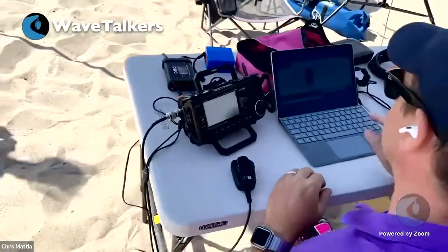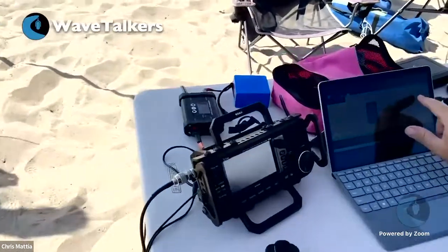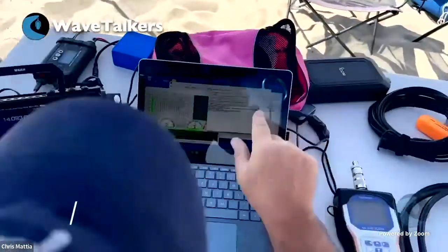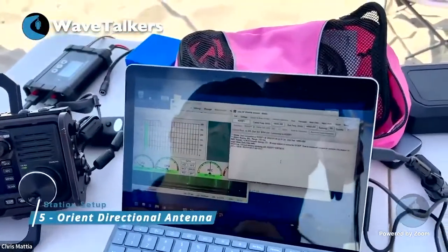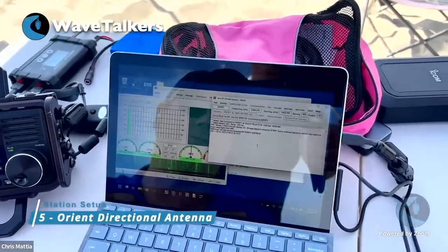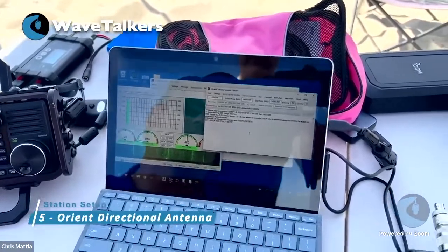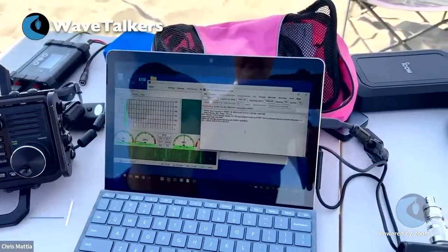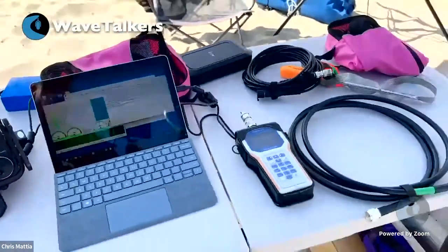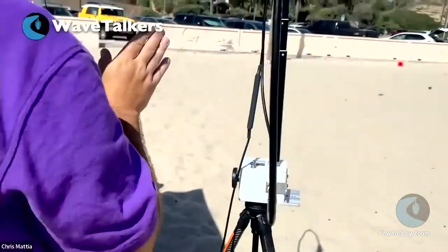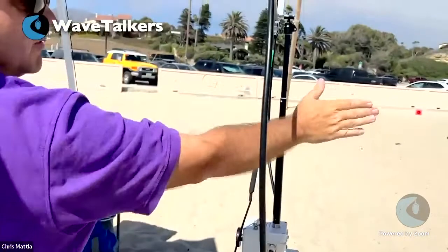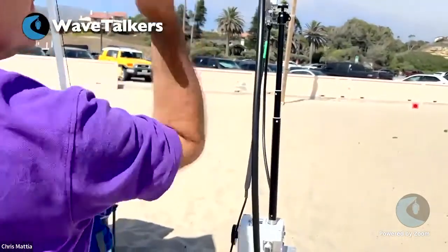And so what I did was when I brought up a favorite, I can see that from my home QTH, it's a bearing of 63 degrees. Well, I'm maybe 20, 30 miles away from my home QTH. So the bearing is going to be still pretty close to the same. So I rotated the Chameleon F so that it's on the correct bearing. So the F loop has a null that runs right through the loop, and it's directional in the direction of the loop.